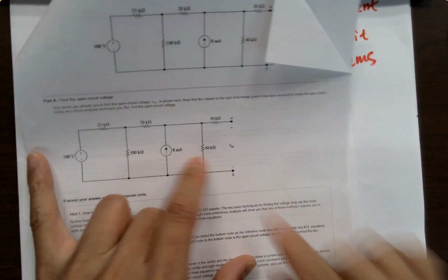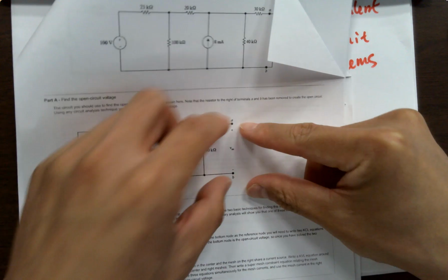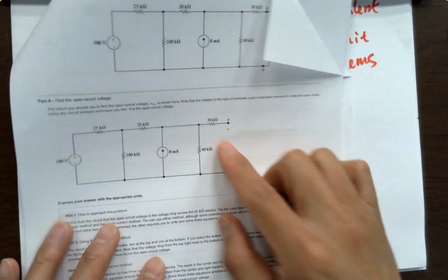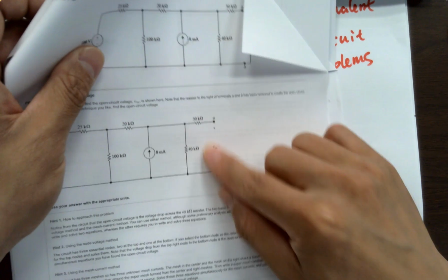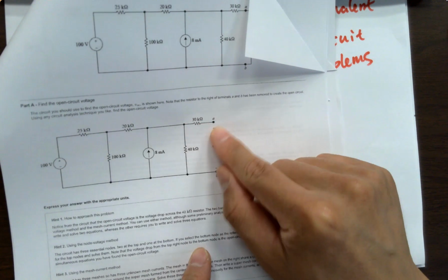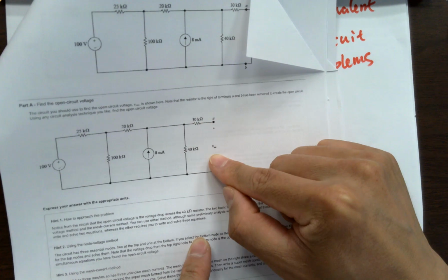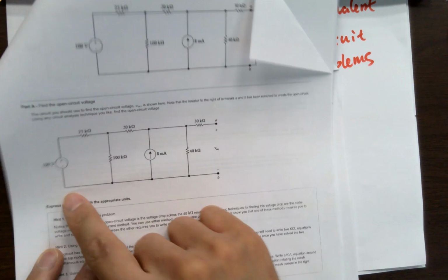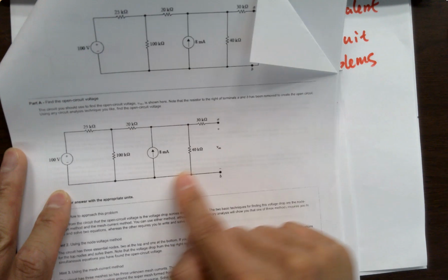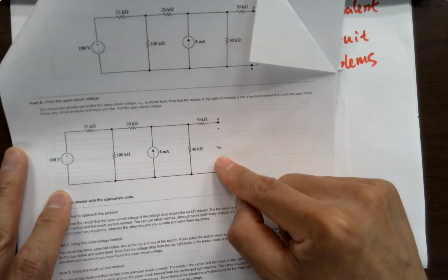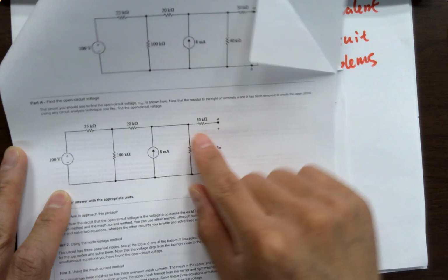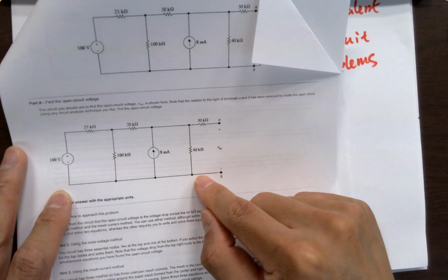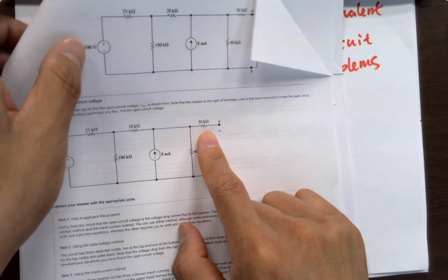So you can see this one, you've got the load removed already, right? So it's just an open circuit. You can connect your load to it. Any load, can be a motor, can be a resistor, can be a capacitor, can be anything. This is your design, right? Just keep it open. Is there any current flowing through this if you remove the load? No, because it's not a closed circuit. It's an open circuit. No current is going to flow through it. Okay, this is grounded. All these are coming back. But nothing is going through this one because the load is removed. But if you plug in your load in here, you'll definitely get a current flow through it because the load is going to connect from here to here and flow current to the ground, right? But now if you remove it, there's no current.